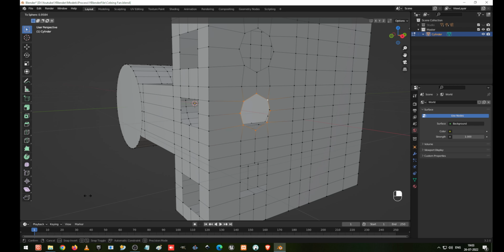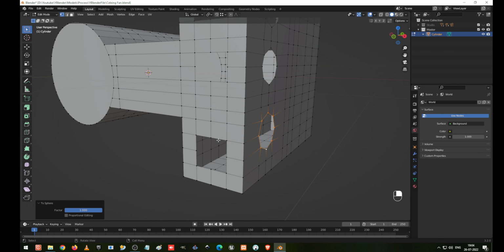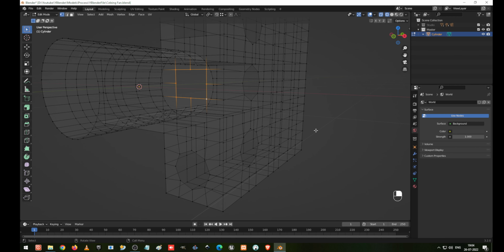Select this. I show one more shortcut: Alt Shift S, press 1 and enter. So this is one more shortcut to apply the scaling. So I'm going to do it for this also. Alt Shift S 1, select this using Alt key. Now it has been selected, you can see it in wireframe.